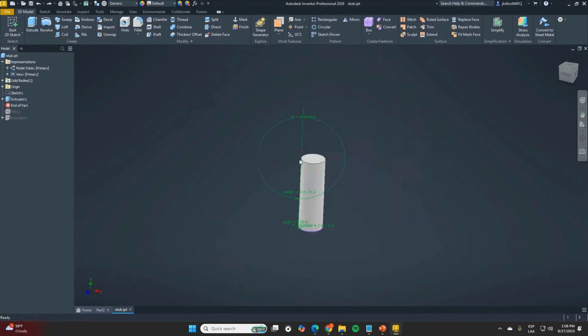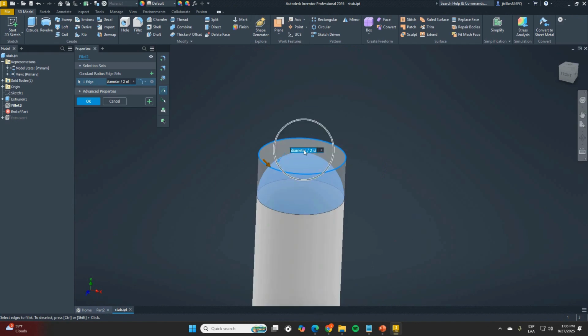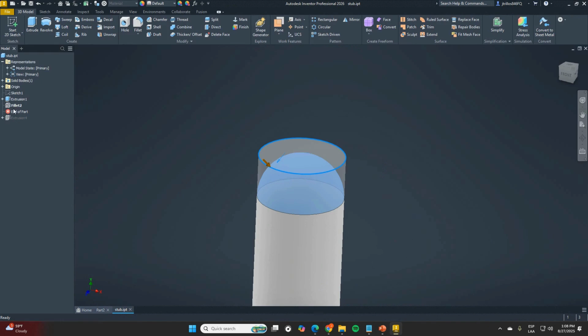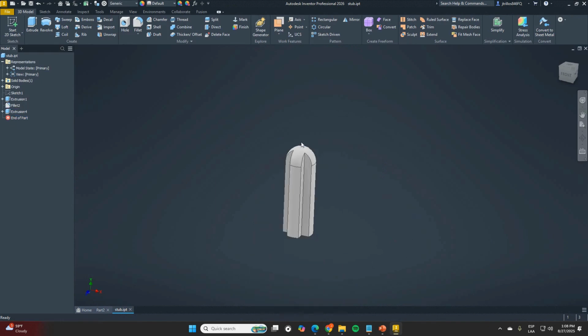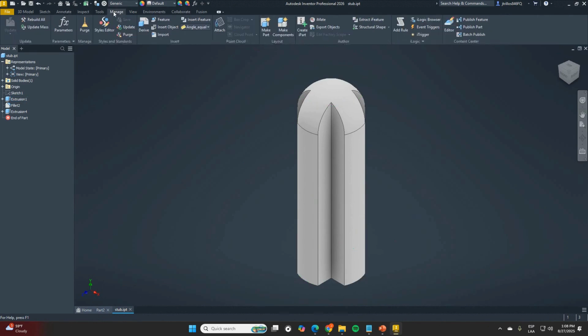And I'm constructing a part from those two parameters with a certain fillet, which in this case, notice that the radius for this one is half the diameter, and another extrusion that's cutting that portion out, all right? So this is gonna be the base for my iFeature. So I'm gonna go right here to my Manage tab, and I'm gonna hit Extract iFeature.